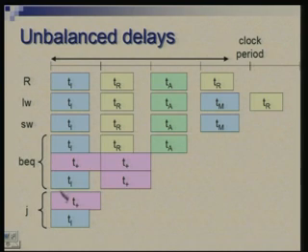So T plus is dominating, and you would notice that even these instructions, although they are taking 4 cycles, are taking longer than what they were taking in the single cycle approach. Of course, LW was in any case taking longer than single cycle, SW is also taking longer, and in BEQ there is a little bit of saving. There is of course still significant saving in the jump instruction, but there are very few jumps anyway in the whole program.